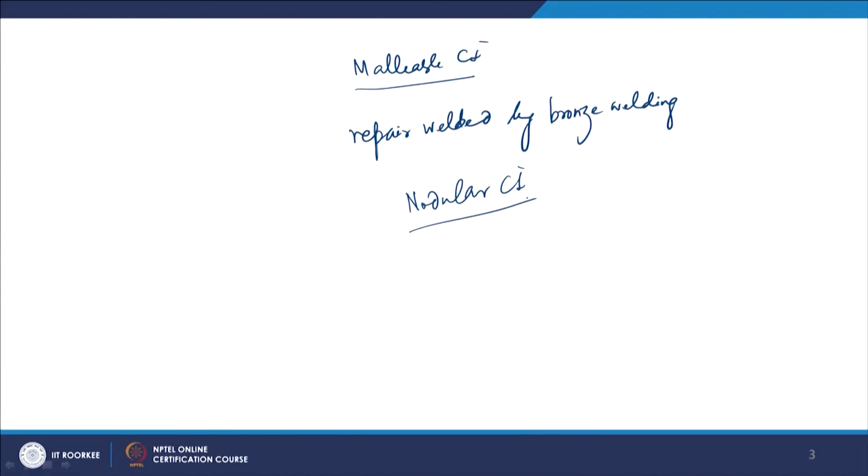If you talk about nodular cast iron, it faces the same kind of difficulty as malleable cast iron, because the nodularization is done by elements like magnesium, and when you heat, if there is loss of magnesium, then the nodularization is gone.